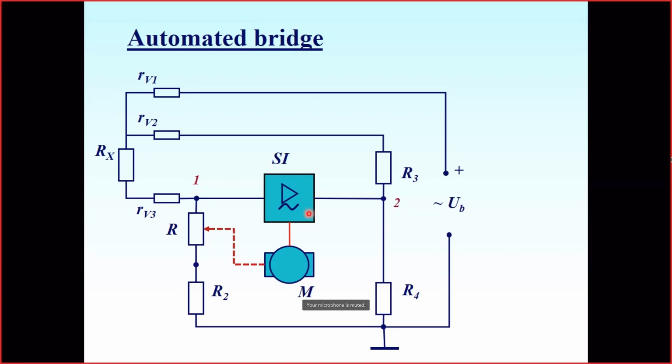If it's lower than a certain negative level, we switch the motor with the reversed polarity for the motor to turn in another direction. In the other case, maybe we just use this amplified voltage and power this motor via some kind of buffer, or a emitter follower, to just control the motor automatically.